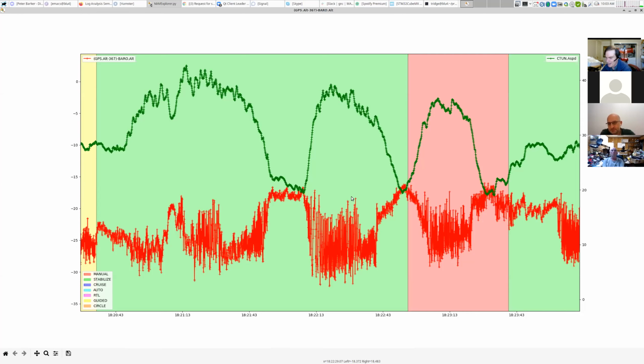Yeah. So a little piece of sticky tape, as Paul suggests, would very likely solve that. Or it could be the holes going into the fuselage. There's all sorts of things, but the simplest thing for him to do. We don't know what that looks like. Is it exposed to airflow? It's possible that the fuselage, because if it's inside a fuselage, it sees the pressure inside the fuselage,